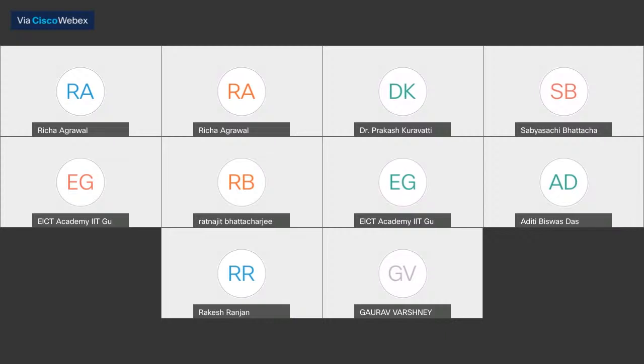And many times this is important because we provide polarization diversity. What does it mean? From the same antenna, suppose I want to transmit one signal which is X polarized, another which is Y polarized. So I transmit both signals. Now, when I am receiving, suppose I am receiving X polarization in one place, Y polarization in another place.